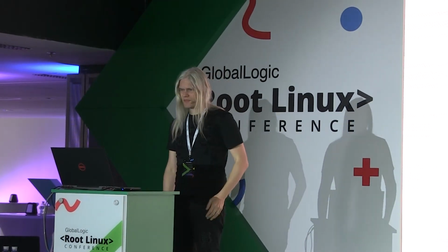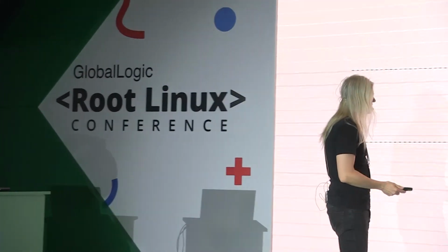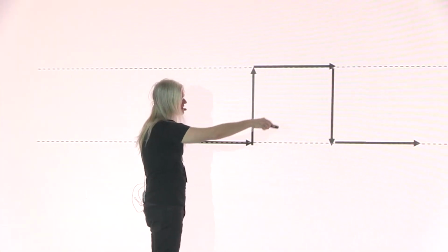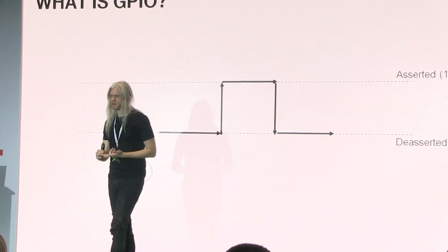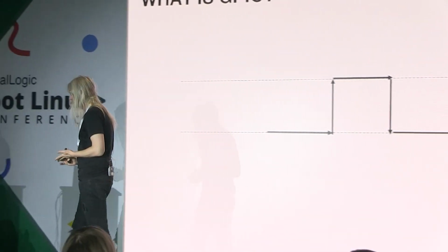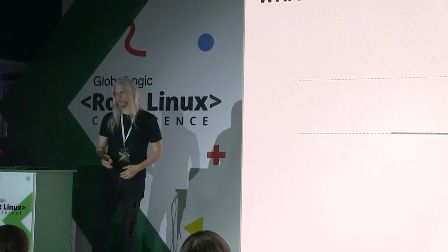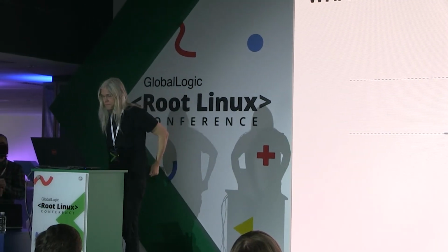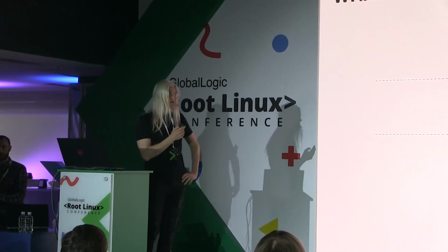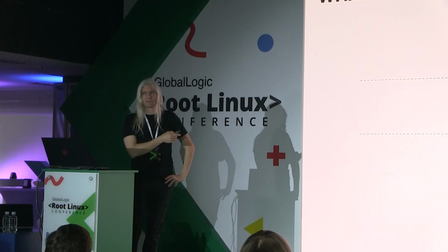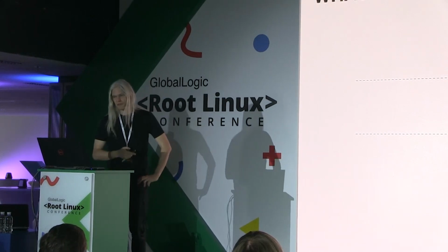And then another thing you will run into is edge detection. So we can detect these edges if we're running it as an input. It comes up here, it comes down there, and there are synchronous and asynchronous edge detection. The synchronous one has digital logic and a clock. The asynchronous one is an entirely event-based thing that is analog. And many GPIOs, for that reason, also are interrupt controllers, because you want an interrupt when you get an edge or an event on a line, like so.